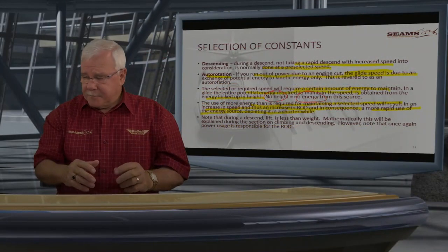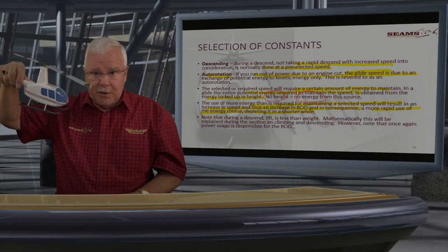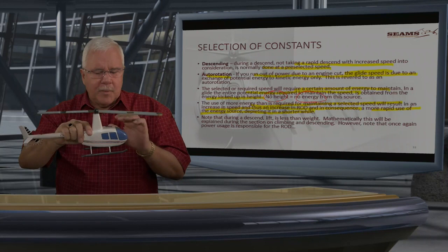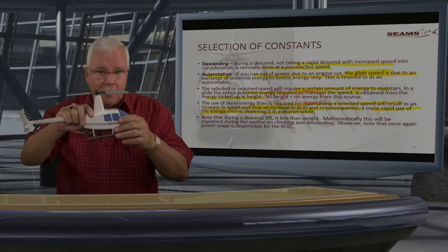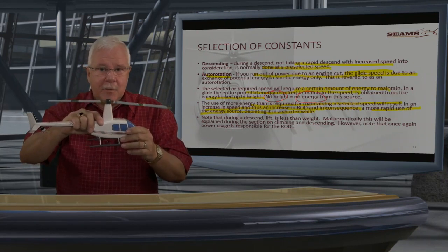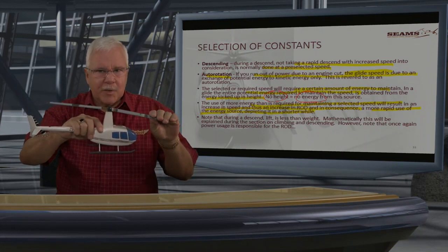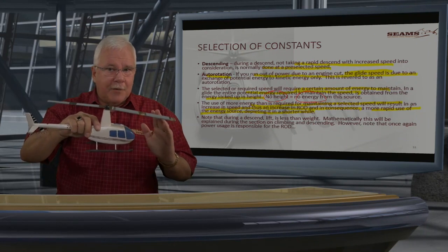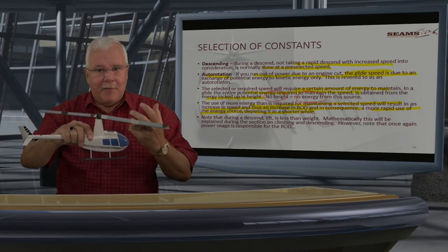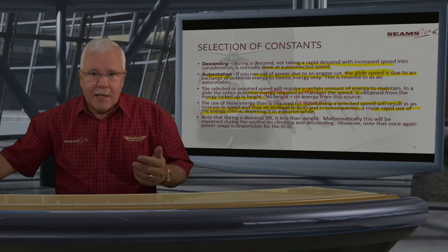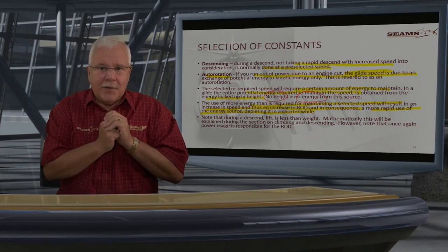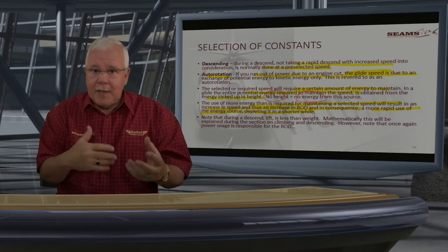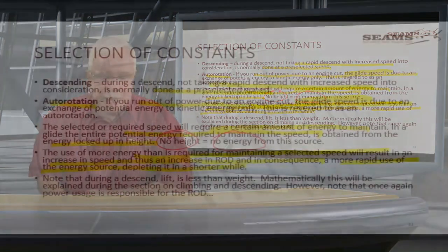it will happen quickly. So the quicker I fly, now in auto-rotation there's going to be speeds where we normally auto-rotate, but there's speed that we will auto-rotate a little bit faster. It will give us a little bit more translation lift and give us a little bit of distance. But the moment you've got over that speed, then all of a sudden the drag becomes the main factor. So don't think that everything can just happen in any direction without penalties being built in. Penalties are built in all the time.